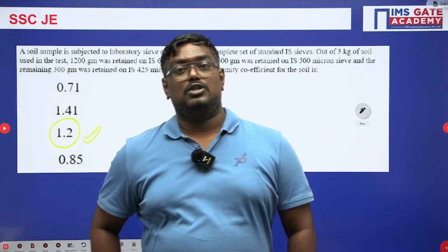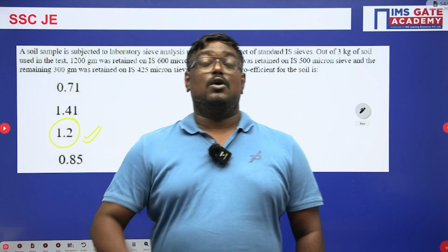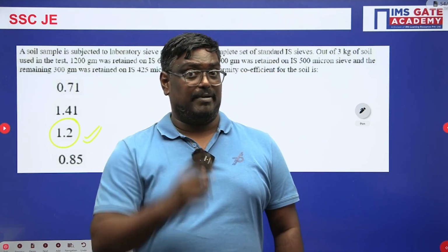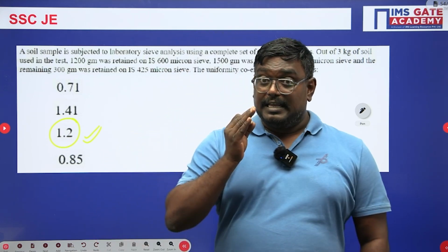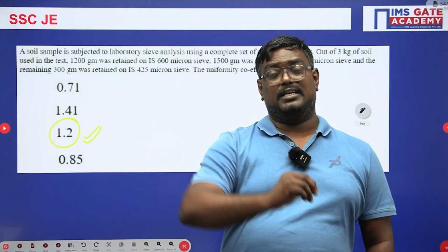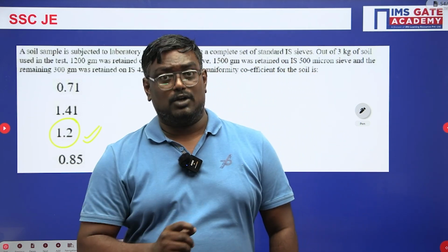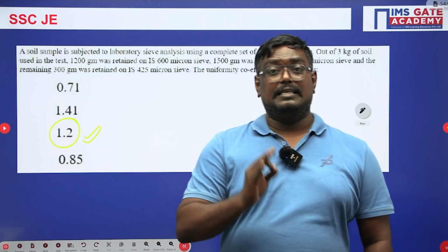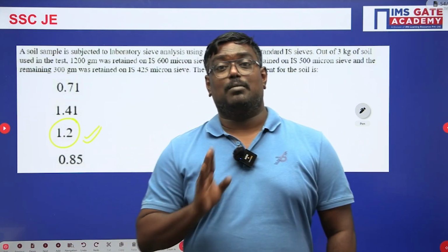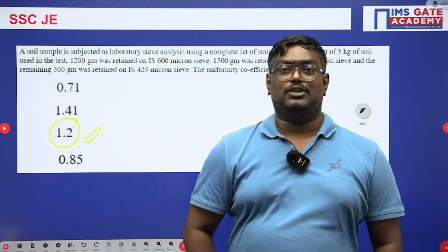Permeability is proportional to the square of the particle size, where rounded particles are more permeable compared to angular particles when coming to shape effect. Permeability decreases with increase in void ratio because both are inversely related. Actually, the formula says in a different way. It is a paradox. And remember, permeability increases with increase in temperature with a decrease in viscosity. Fully saturated soils are more permeable when compared to partially saturated soils.